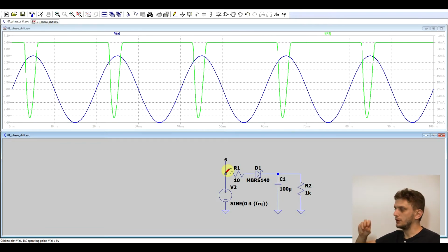And with this kind of load, we don't just care about the phase shift, we also care about how distorted the current is, since both of these factors have to do with the total power factor of the circuit. Now in this case, the distortion isn't causing power to go back into the power distribution network, but rather it's causing power to be drawn in a non-efficient way. So if you're drawing current like in this circuit only in very brief periods of time, rather than having it spread over a wider time range, so throughout the sine wave, then you will need very thick wires to supply the current, much thicker than if you would have a linear load.